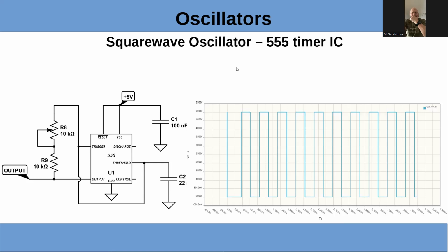Okay, so R8 controls the frequency. R8 and 10, but yeah, R8 is the variable. It's a combination of these and the capacitor, which is the time constant.